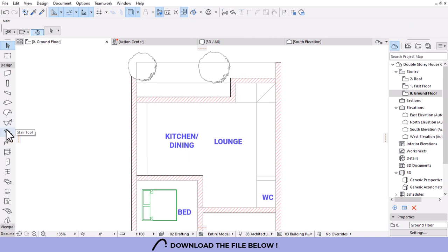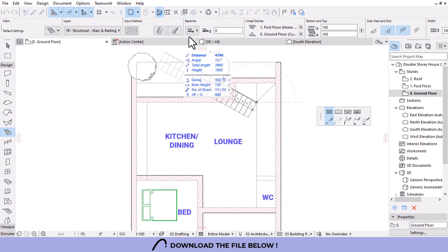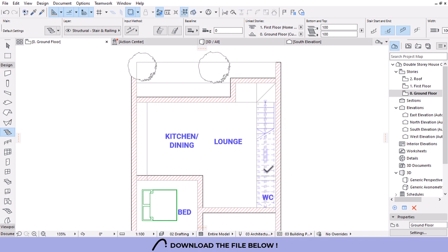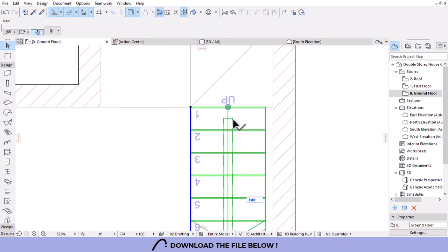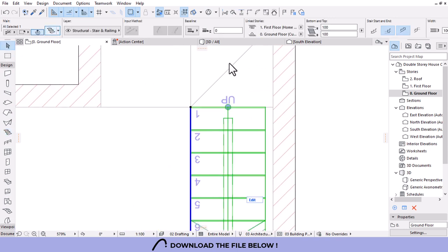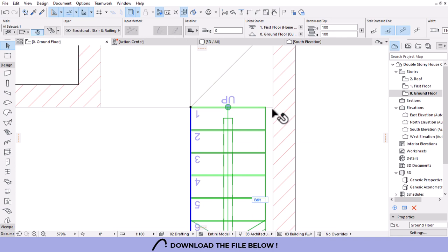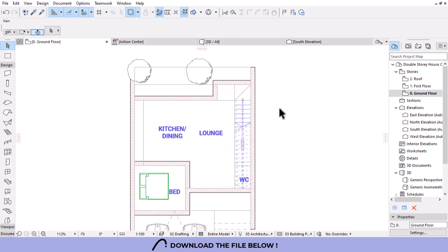and draw the staircase. So I'll just click here, and then I would make sure the baseline is on the left so that it can fill here. So I'll just draw like that to there, and then okay, from here let's zoom in. I'm having an issue here with the width of the staircase, so I'll select it and then open its settings to set the width to 1.1 so that it fills the whole area that I've created for the staircase. Perfect. So from here, there we go.